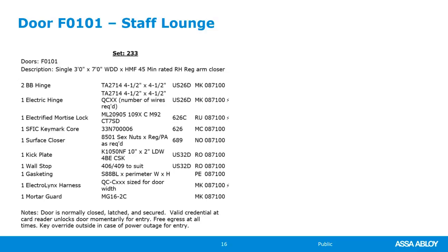The other thing is, if this were a single door with a power operator, then yes, I would use an electric strike, because the electric strike allows the latch bolt to push past the keeper and the door can open without having to have any kind of latch retraction. So there are cases made in both directions. From my experience, that's what I have seen. Any other questions on this opening?